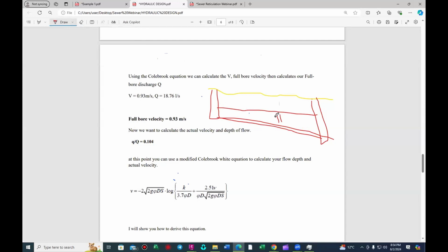It will decrease. I'm sure you watched the illustration in that video that if you decrease your slope, then you also decrease the cleansing velocity in that pipe. So you need to strike a happy medium here: your sewer doesn't have to be too deep, and it doesn't have to be too flat. It has to be flat enough such that your pipes can achieve full bore velocity, but it doesn't have to be too deep, because that can make the whole project very expensive.